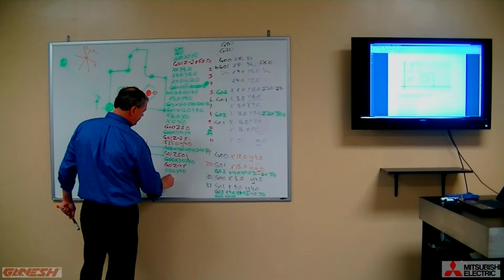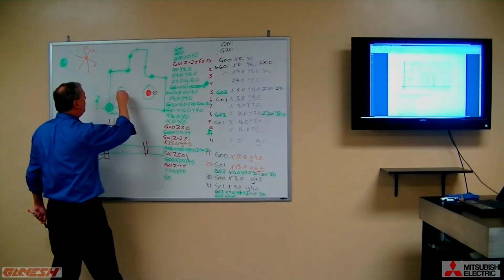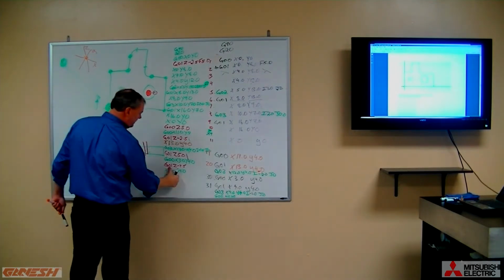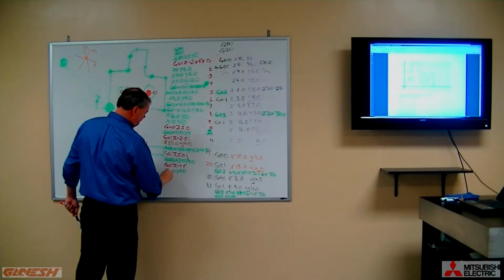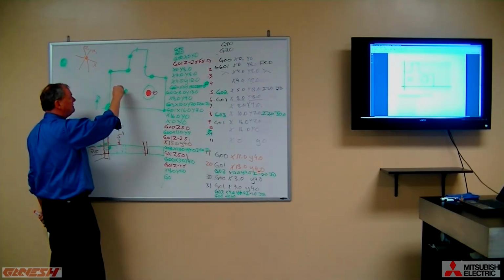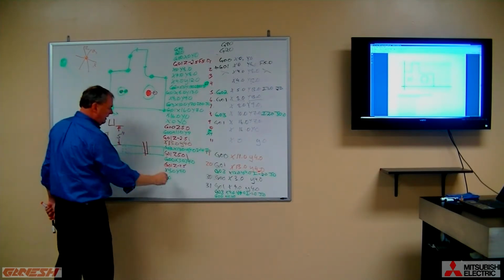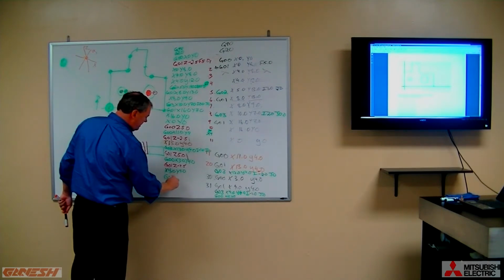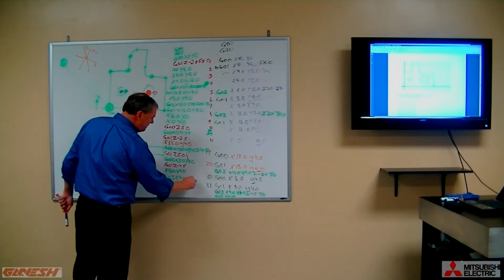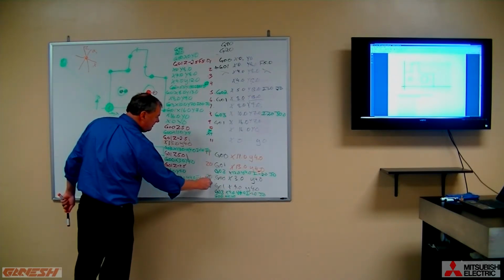just say G03. I'm sorry, we're going over to X4.0, because we're positioning right here. 3.0 in X is this center point. 4.0 is that point. So here we are at X4.0, Y4.0. And now we do our G03, bring it back, X4.0, Y4.0, I minus 1.0, J0.